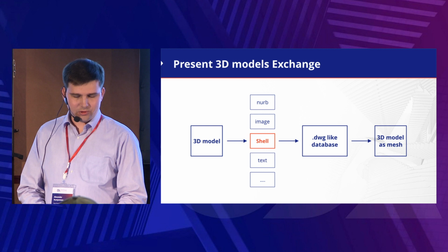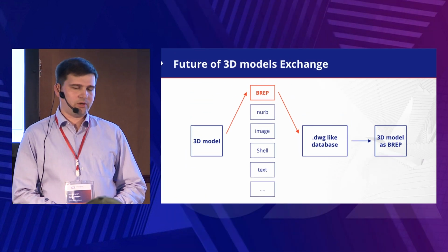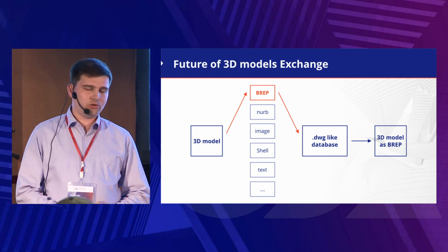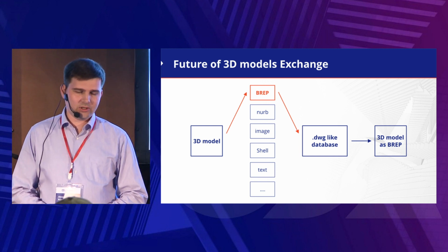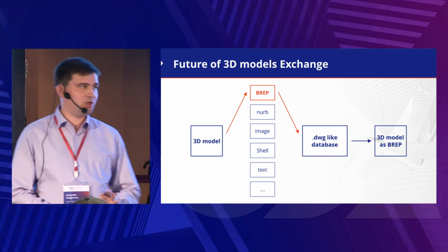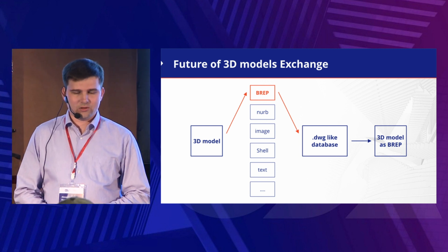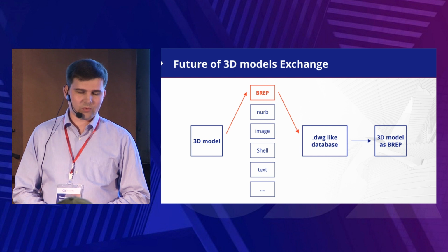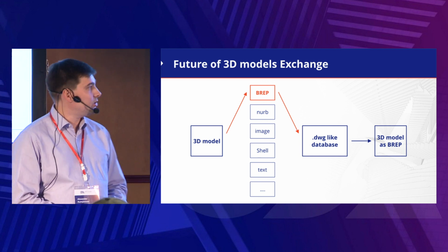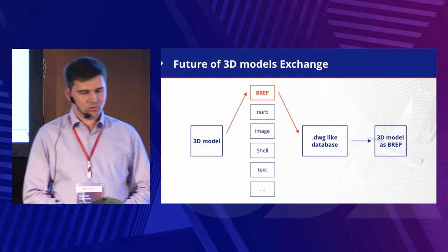This is the present situation. In the near future, we are going to provide the ability for Visualize SDK to work with BREP directly. In this case, the 3D model can be stored into the DWG-like database as a BREP representation. And in this situation, we will be able to export the 3D model not as tessellation or as mesh, but as a BREP model.